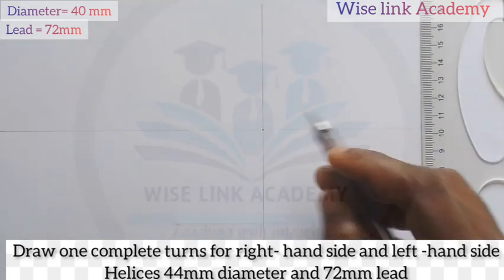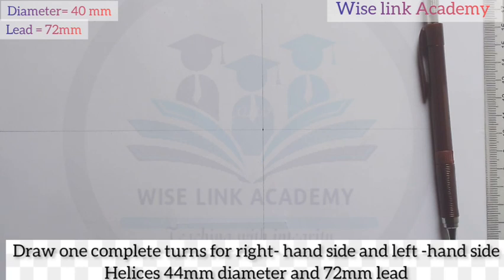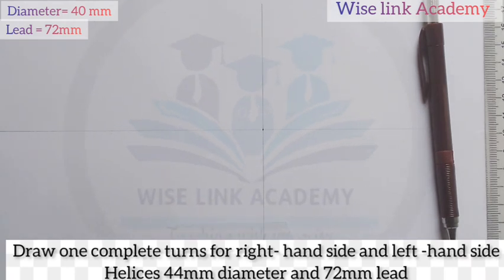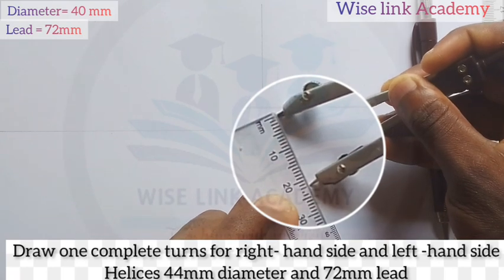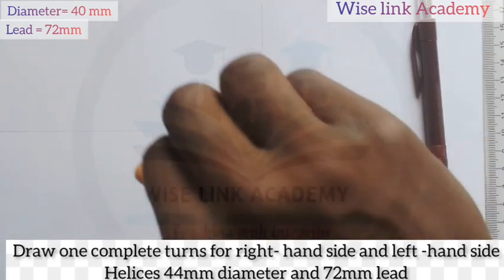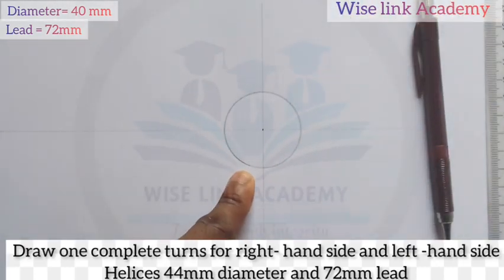At this point, my first dimension is given to be 44 mm diameter. And we always say that whenever you hear the word diameter as a parameter in technical drawing, divide that parameter by 2. So 44 divided by 2, I'll have 22. From here to here becomes my 22. At this center point, I will place it there to draw a circle this way. So here is the diameter of 44 mm.